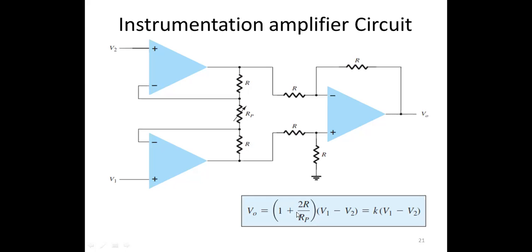The value of the potentiometer is adjusted, and this resistance is appearing in this formula. If RP is adjustable, and it is changing, this factor will be adjusted according to the values of the potentiometer, and this multiplier factor can be varied as per the design.